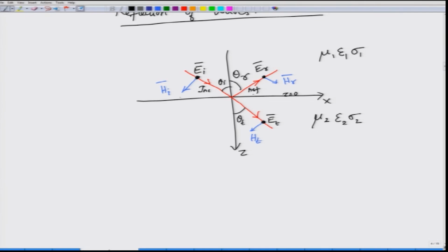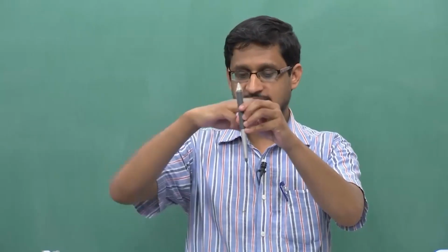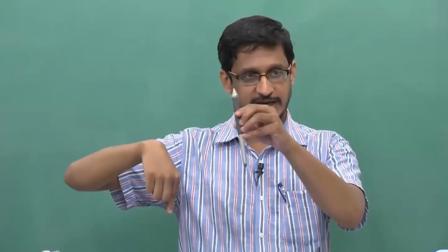Look at the orientation of the magnetic field lines which are shown by the directions in blue color. Okay. So, for the incident wave the magnetic field is directed in this particular direction, for the reflected wave it is directed here, and this is the direction for the transmitted wave. Does it make sense? Yes. So, you have to now think that the electric field is perpendicular and coming to you. So, E cross H will be going along the K direction.